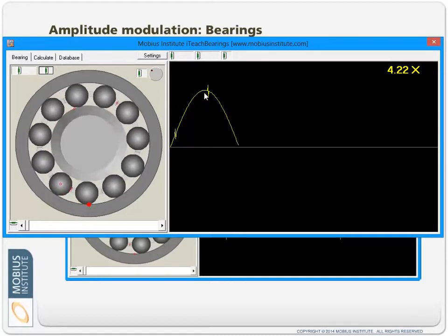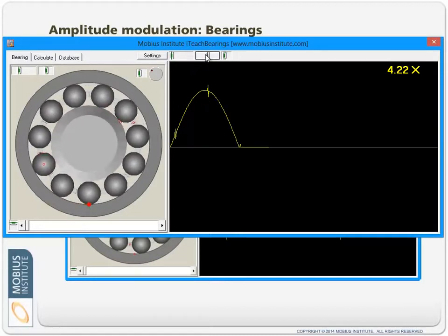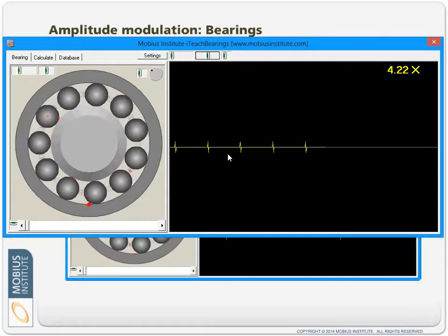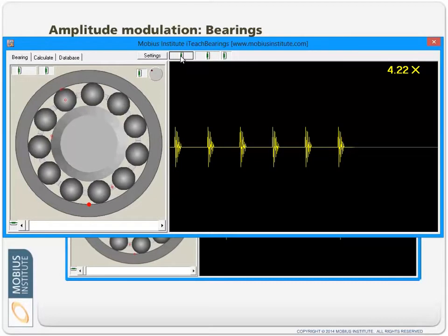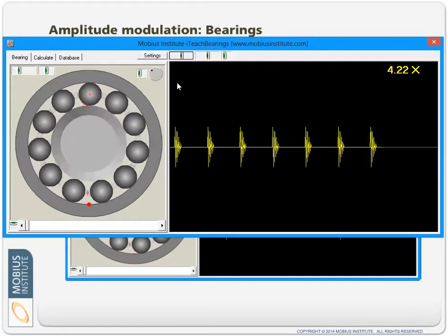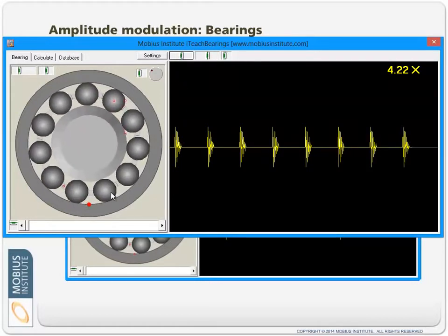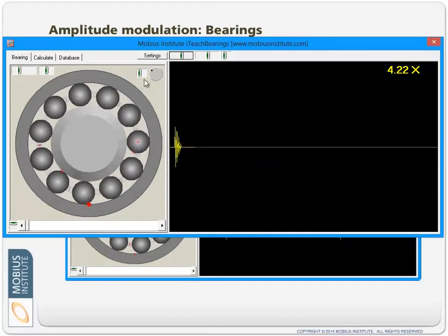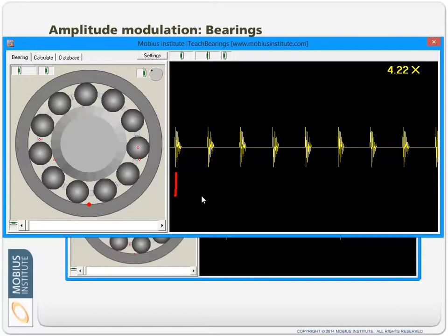little spike. Now what I'm going to do is remove the sine wave, the 1x vibration, and just look at the spikes, and I'll give it a bit more amplitude. So what we're seeing here is that as each rolling element impacts this point, we get a spike of vibration. This is the ball pass outer race frequency, so it's ping, ping, ping. This little ring down here is the resonance, or the stress wave. Let's not get into all that for right now.